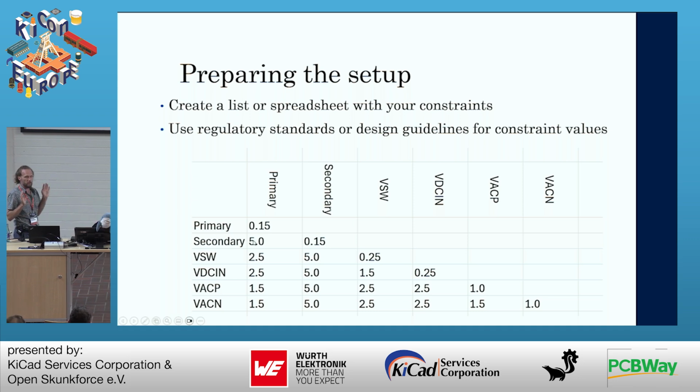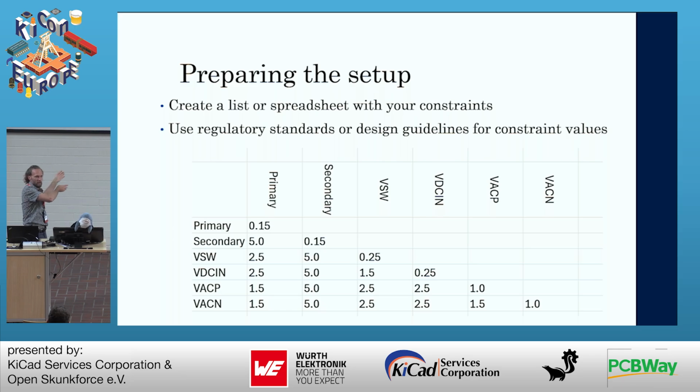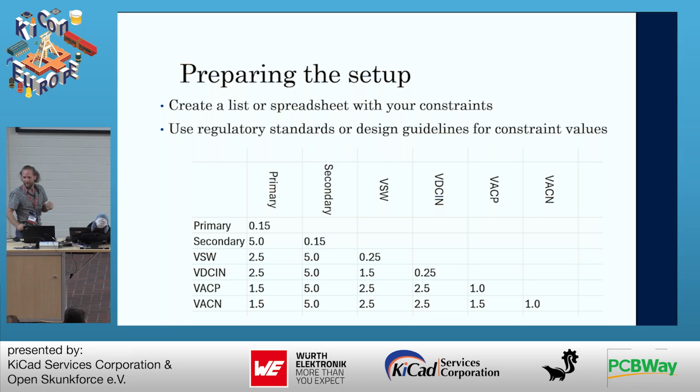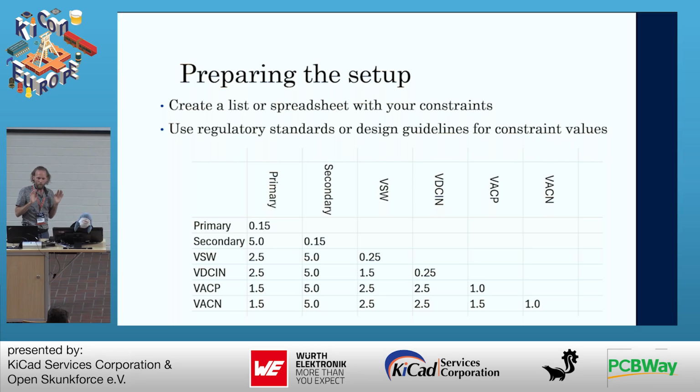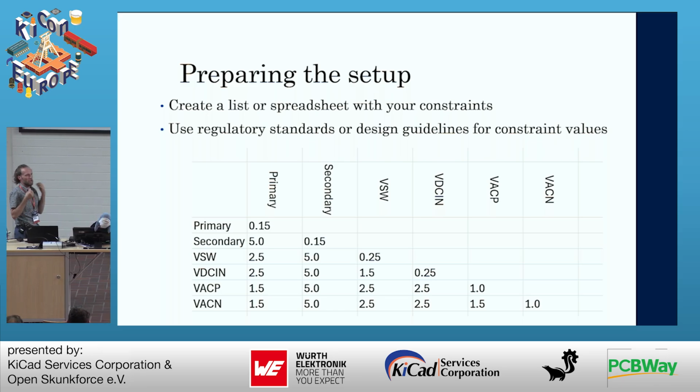Again, if you're doing high voltage design, you better consult somebody who knows what they're doing and ask for your numbers to your design. Don't take my numbers for it. This is just something that could be totally made up. Don't kill yourself. As I said, we're not talking about the actual high voltage design here. We're just talking about the concept of a voltage barrier or an isolation barrier between the primary and secondary side. So I set that to 5 millimeters.